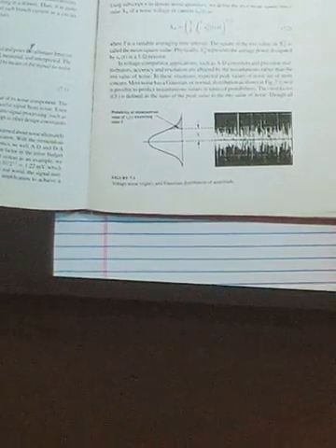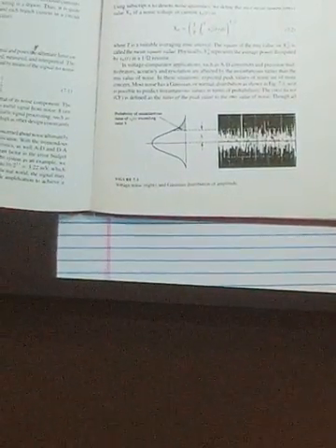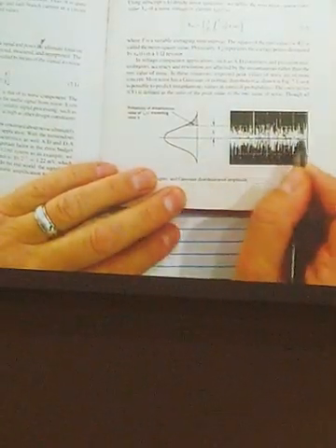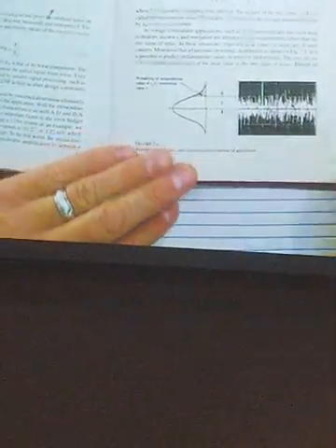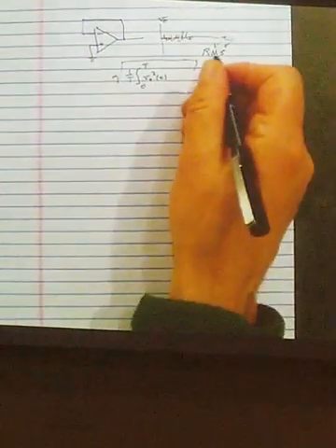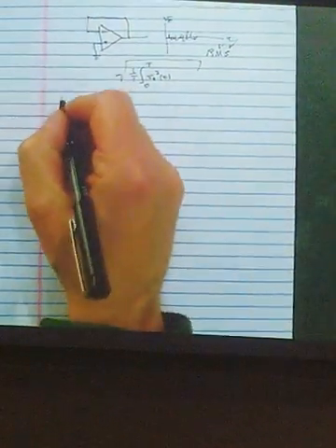And kind of a rule of thumb, and it's just a rule of thumb, but if you look at this sort of band of noise here, that's going to be about the standard deviation. So somewhere here in that bright band, that's about the standard deviation, or in other words, the RMS value of that.